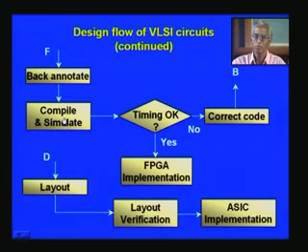Most probably functionality is okay, but you don't know whether timing has been really met. Let us say you are simulating still at 100 megahertz, whereas the previous tools, say Xilinx, also give a revised estimate of the frequency of operation, and that is the final. The synthesis tool also gives that one, but that is rather a rough estimate only. It doesn't actually reflect the true thing. Only the vendor specific software will reflect it, and that is place and route of Xilinx, which we have seen earlier. And here, if this timing is too close and if it is slow, then you will have timing problems.